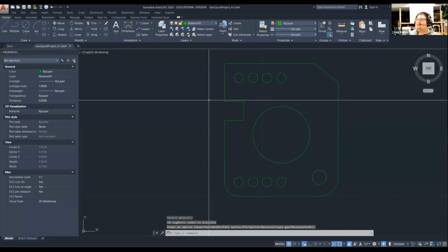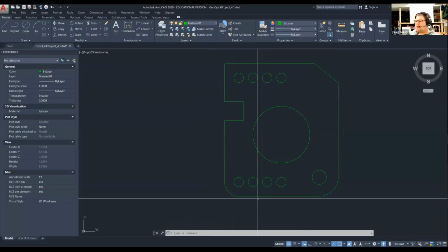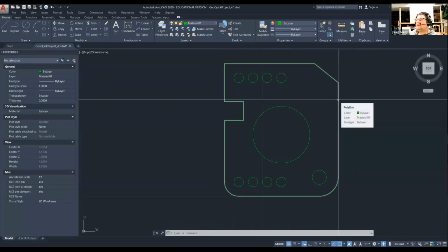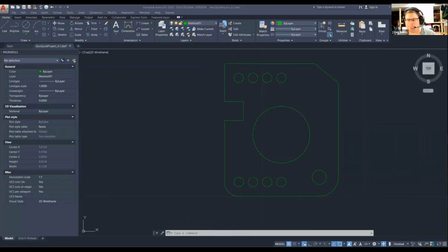There we go. Now pick one of your segments, just to make sure that you glued it together. Okay, yep. So now it's glued together as one object. That's the right way to do it. And so when we get to the next step, we're going to extrude that piece a 1/4 inch in the Z direction to make it a 3-dimensional object. So you can't do that unless those polylines are in fact closed polylines. Oh. All right, so very good. Any questions?